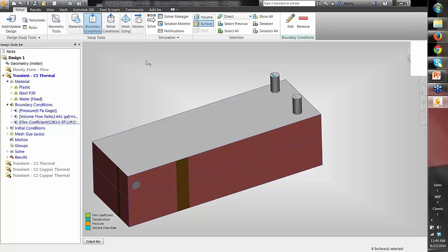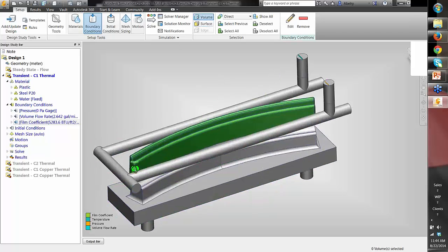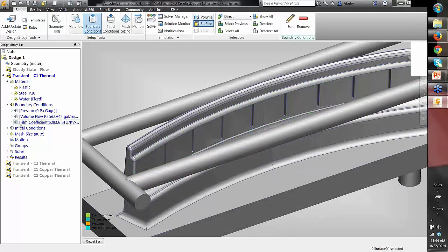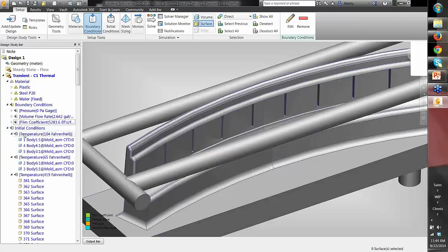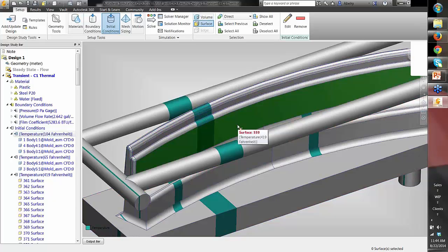But now the assumption that we make is a little bit different. If we get down to the plastic, you'll see that we assign a plastic temperature to the surface of the molded part. This is when we start to initialize our temperature work, where we're going to start doing the thermal study after the injection process is completed, and really setting up a design of experiments